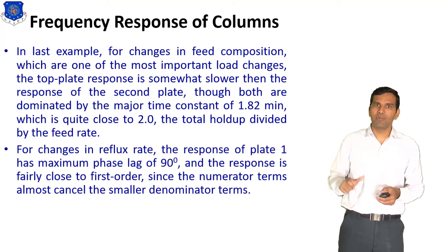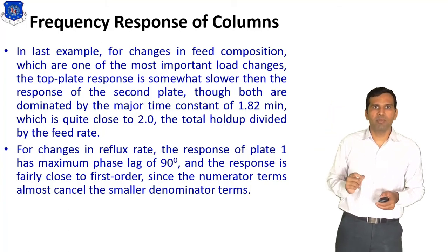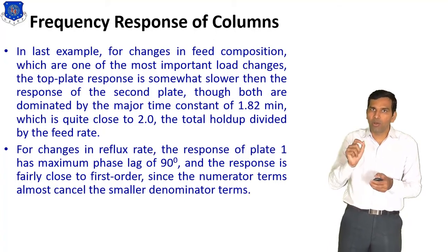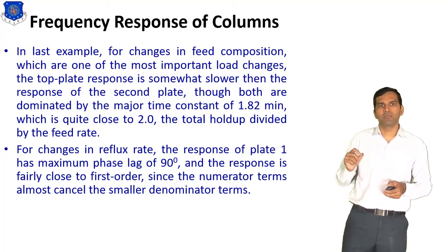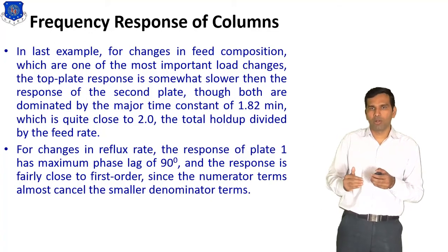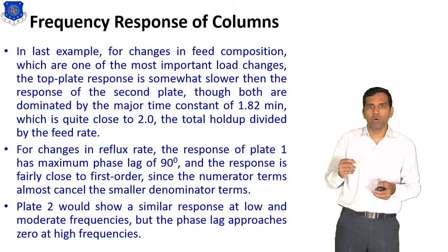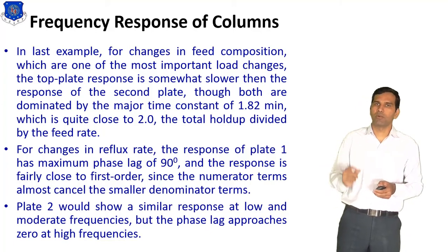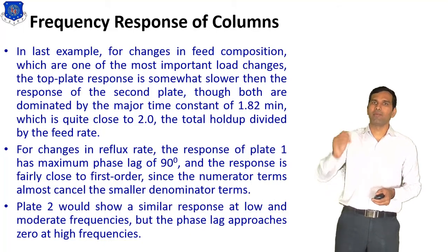For the change in reflux rate, the response of plate 1 has a maximum lag of 90 degrees, and the response is fairly close to first order, since the numerator terms almost cancel the smaller denominator terms. Plate 2 would show a similar response at low and moderate frequency, but the plate lag approaches 0 at high frequency.